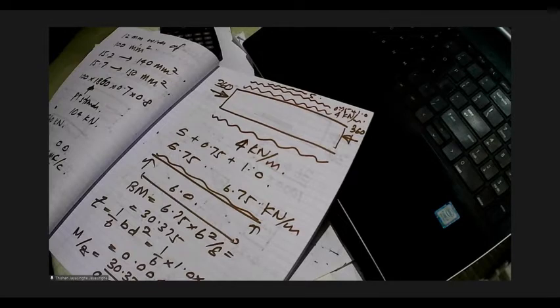So with a 160 millimeter slab, I'm satisfying the deflection criteria over 6 meters. To satisfy the deflection criterion with 160 millimeters in reinforced concrete, you need a lot of reinforcement over 6 meters. But here we are using only 12 millimeter wires at 560 millimeter center to center, 2 wires. So the advantage of PT is you can minimize the amount of reinforcement needed. And you have to understand this is a simply supported slab, not a continuous slab. So in an RC situation, you need about 180 or 190 millimeters for a simply supported 6 meter span slab. Is that clear, Bashita?